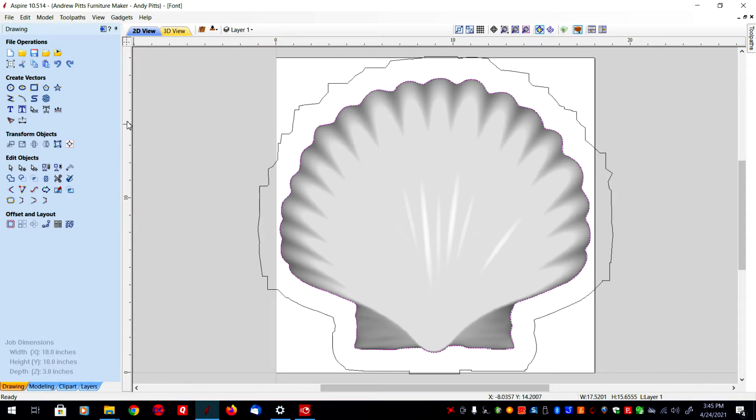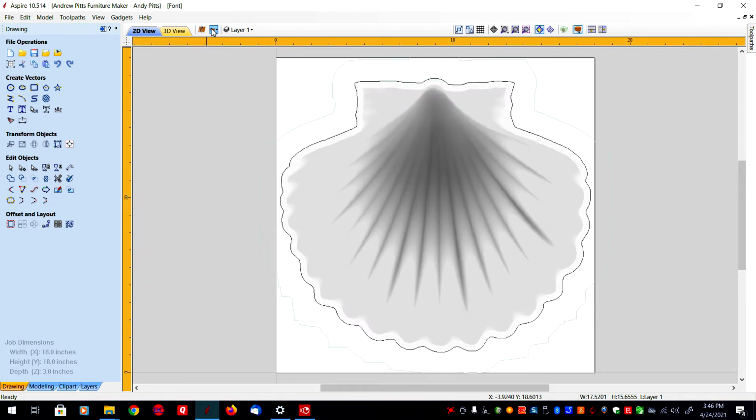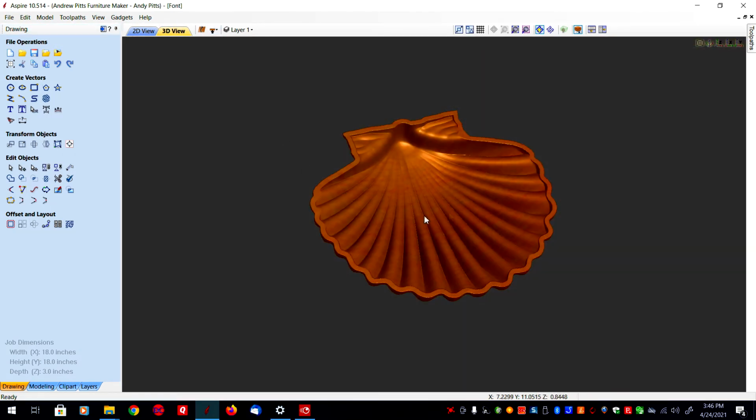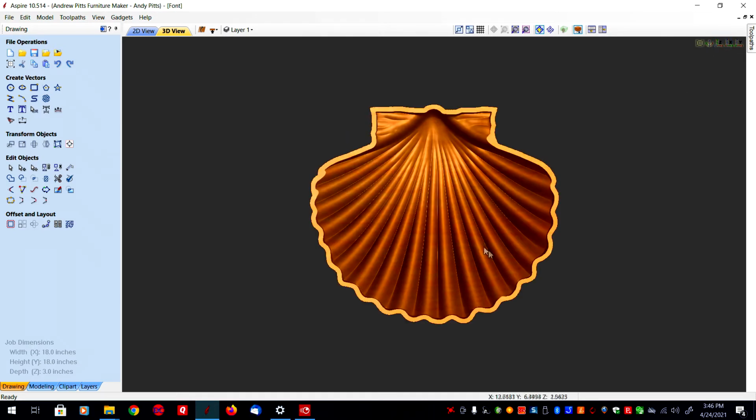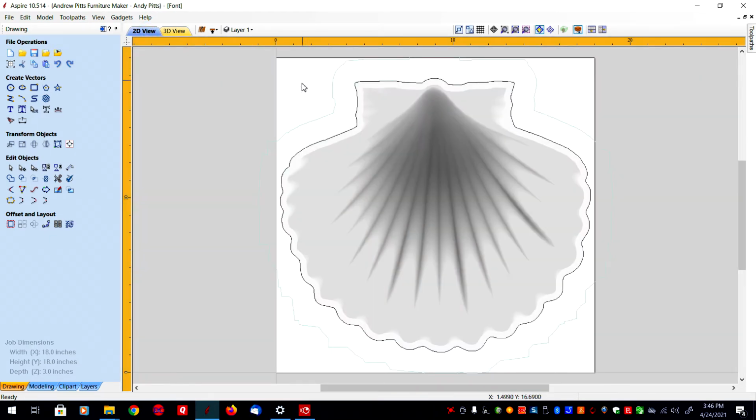At that point, I thought I could probably go ahead and set up some toolpath files. So I thought, okay, I'm probably going to screw this down to the spoil board in the 4 corners, which is pretty much how I always do my work. And if I cut the inside part first, right there, that would leave all this material around the edge, so I could screw against the spoil board.